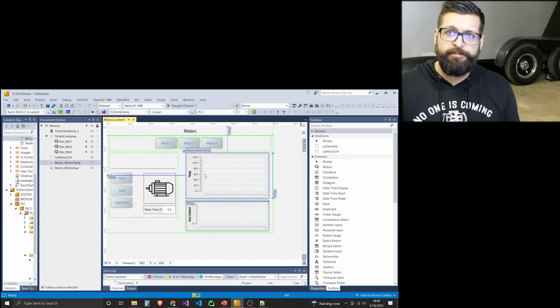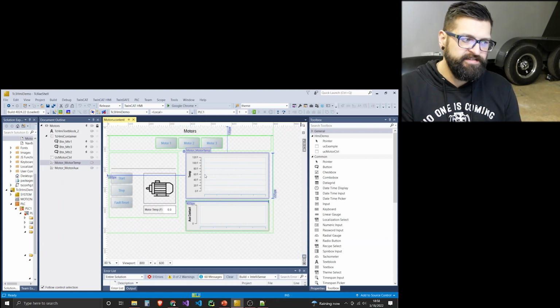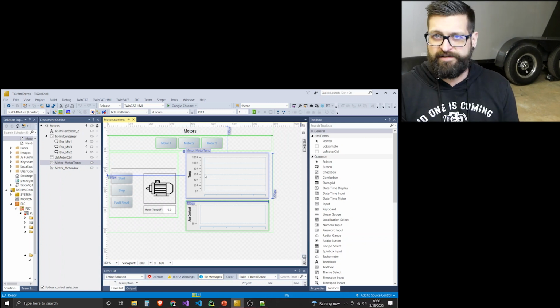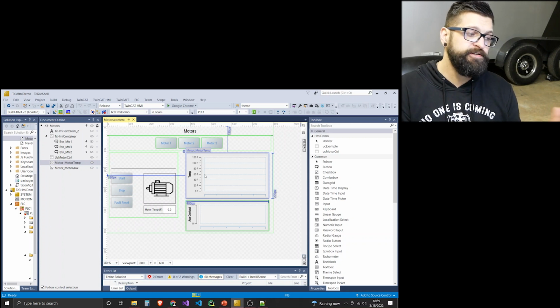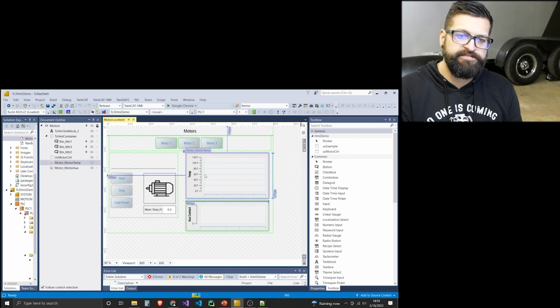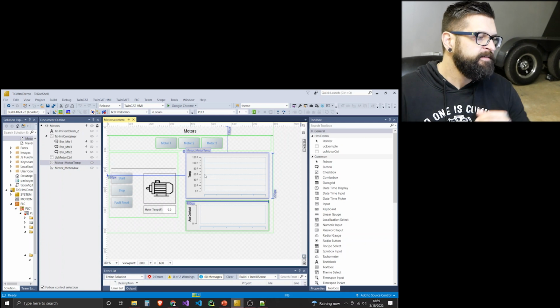You can use the scope if you've got a very fast loop constant. But if you have a slow process, you don't need to see it at the 100 millisecond or 10 millisecond rate. You can see it on a larger time cycle. And so you can use your built-in ring buffer via the SQLite Historize extension to display this data.